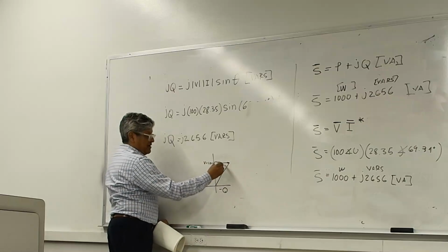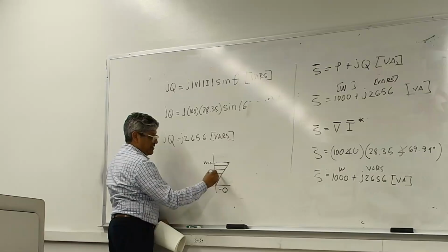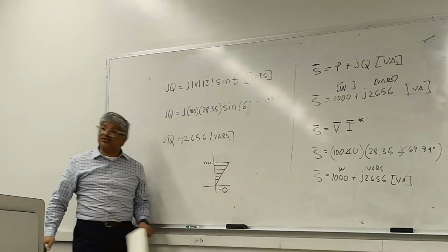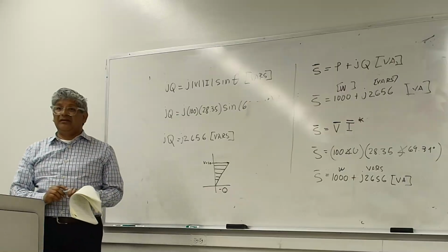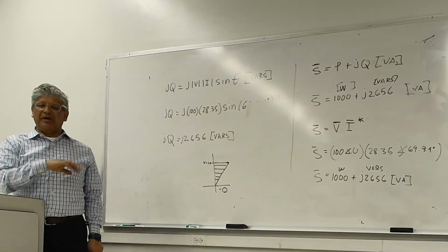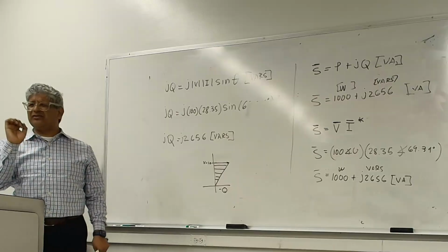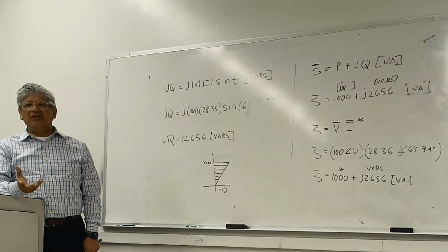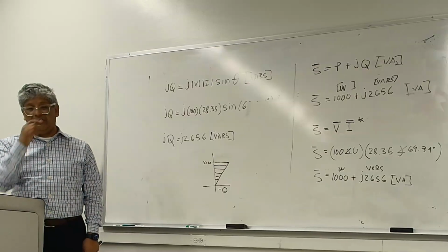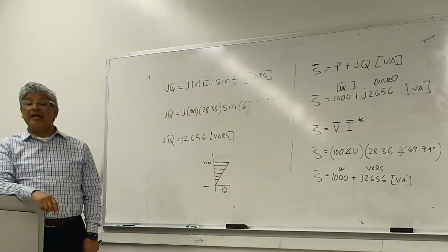As the voltage comes down, the amount of vars you get out of the capacitor reduces linearly. So that's one challenge with capacitor banks. Like I said, we'll do this later in MATLAB so that you guys can get an idea. So that's one of the problems. And when do you need vars? Basically, you need vars when the voltage is going down. So, okay. What about